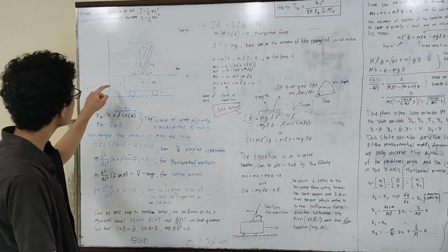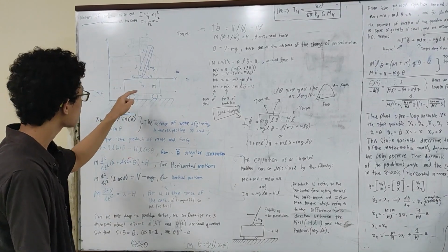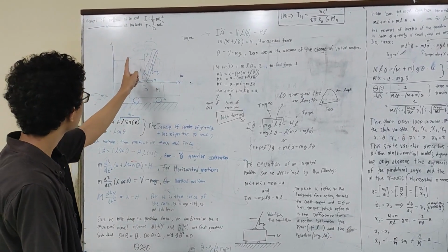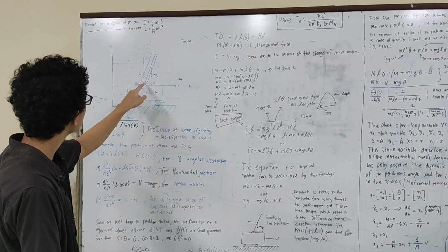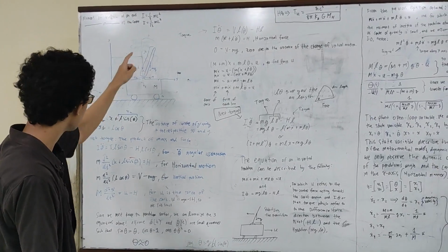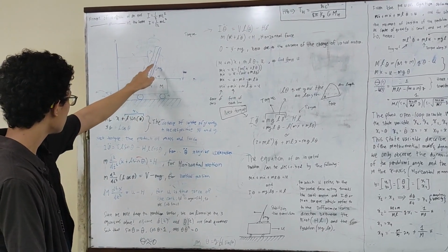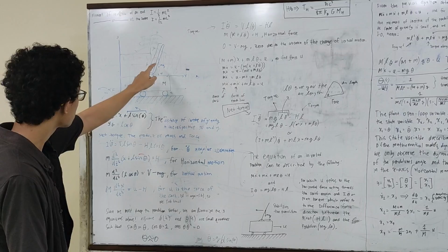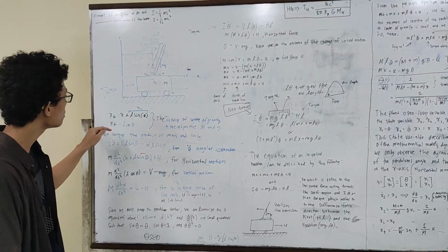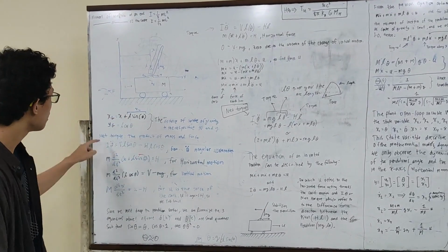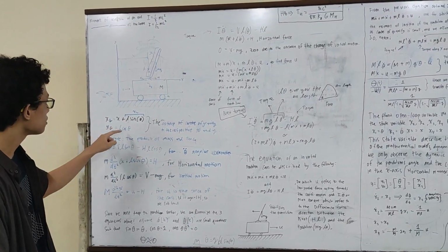So we can use the force U to move the cart to the right to counteract the position of the pendulum moving up and left, by moving it horizontally to the left and vertically up. And to find the coordinates of the center of mass, we can use the equation xg is equal to x plus L sin theta, and yg is equal to L cos theta.